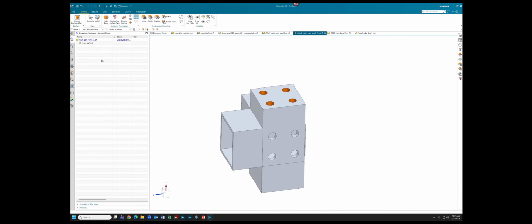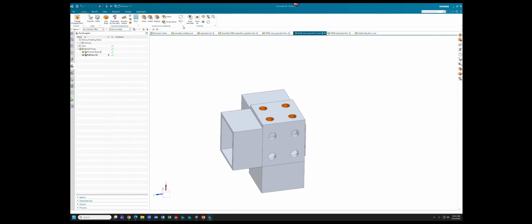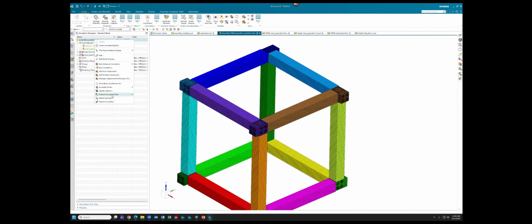This is just so useful for design iteration and being able to quickly play around with design changes in your model. And this is something I use all the time in my finite element model process, often for recommending maybe thickness changes to deal with negative margins or subtle design changes that can be implemented into the design.